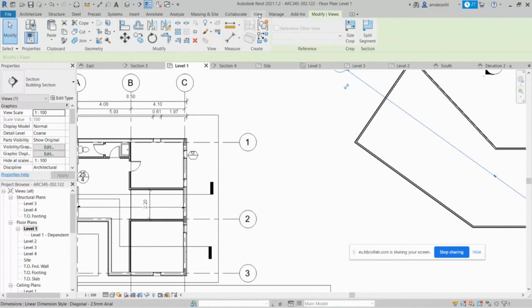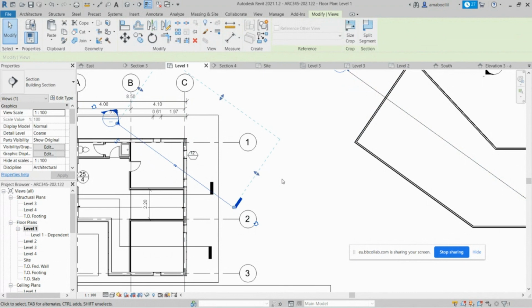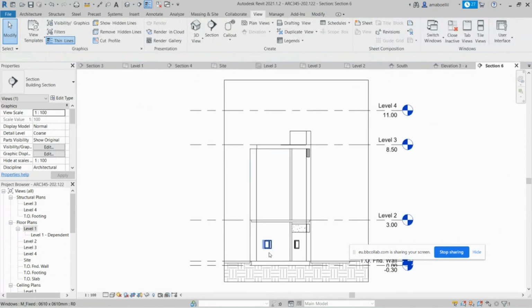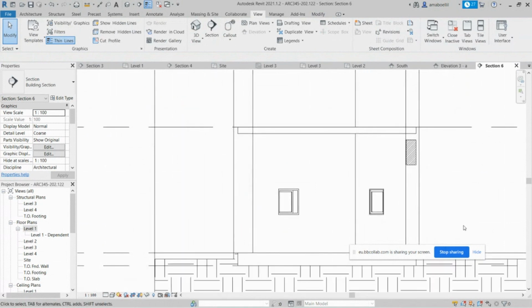And if you have a rectangle like this and you start to make a section in it like this, and you present it, is this reflecting anything useful? No. Because if you show it, the actual window here is not reflecting anything. I cannot tell from the drawing what the dimension of this window is, because this is a projection here as well. The wall itself is also projected, so it's not going to tell me any information.